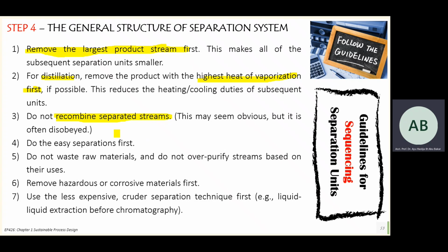But later, once you run your PFD, then you will see, because there are certain streams, perhaps to save cost, you just mix them back. Always do the easy separation first. Do not waste raw materials and do not over purify streams based on their uses. Remove hazardous or corrosive first.